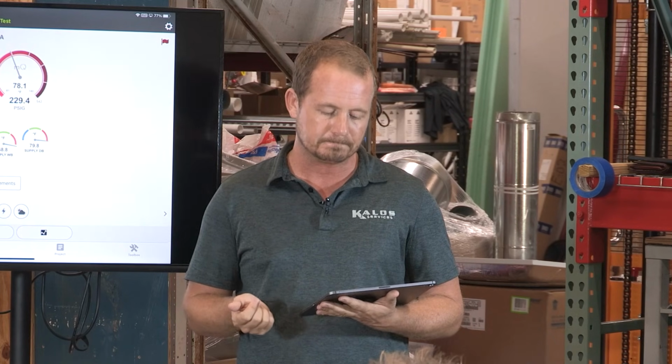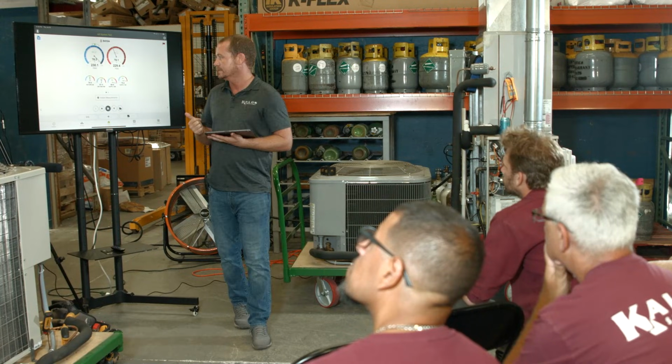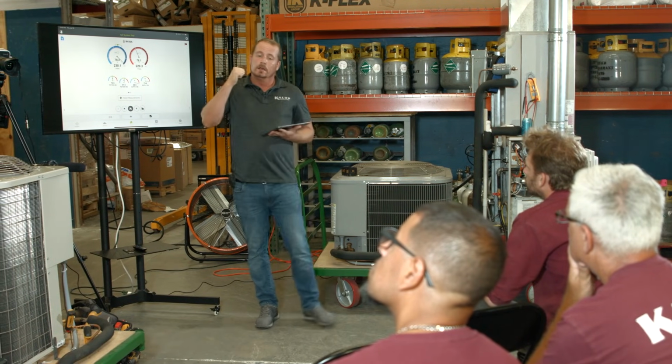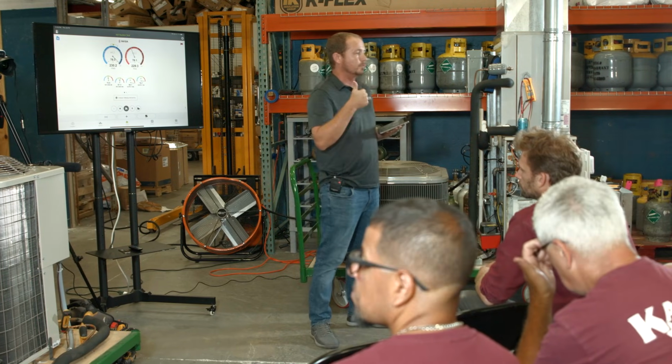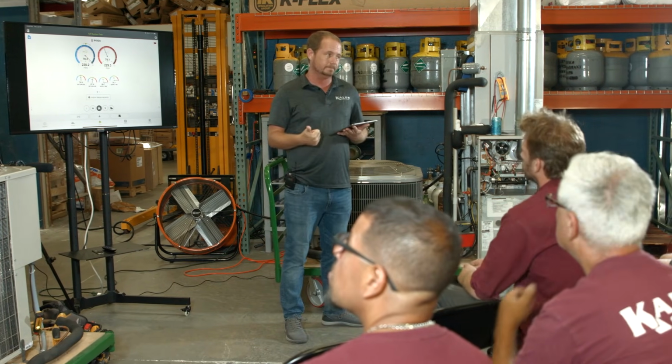The system's off, so they should be measuring the same, right? Okay, why aren't they? Hypothesize. Put them together, run it, let's see what we get. Make sense? So always double check your tools. Before we get running on the system, I do want to talk through quickly about our primary indicators of low airflow.